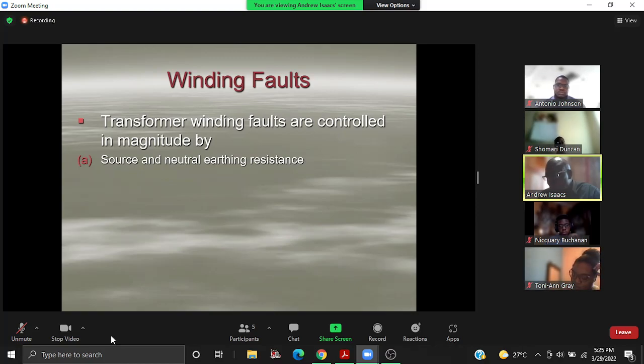You with me? So it comes back now to the science and art. I know I can reduce the fault current by increasing the earthing resistance, but by increasing the earthing resistance, you're also reducing the fault current that will go to your relay. You understand me? All right, I hope you do.